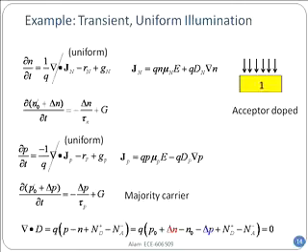It's still zero. The reason is the delta n, the extra electrons that you have created, is exactly balanced by the extra holes that you have created. As a result, even after shining the light on, in non-equilibrium even, the gradient of the electric field is zero. Now, gradient is zero. That doesn't mean the electric field itself is zero. But remember, I do not have any contacts here. So my input electric field is zero and the gradient is zero. Therefore, throughout, the electric field is zero. Do you realize this? And that's why I was able to drop the term.